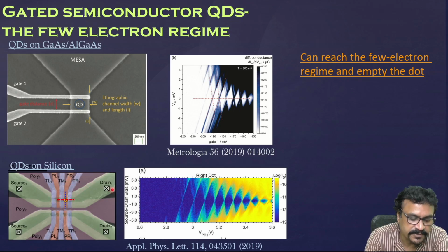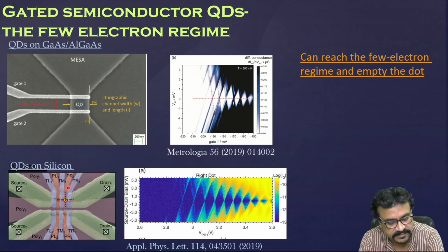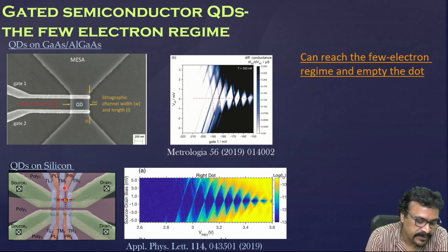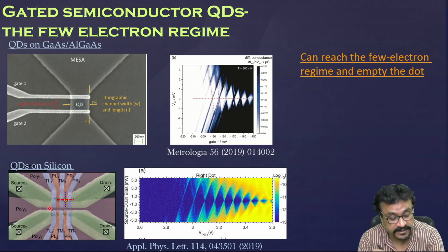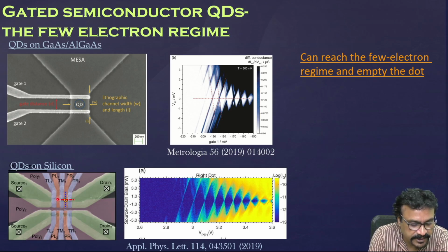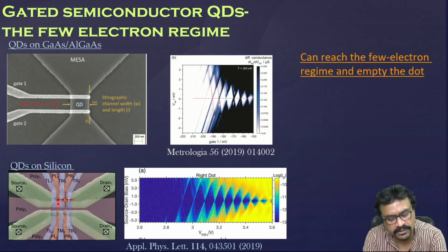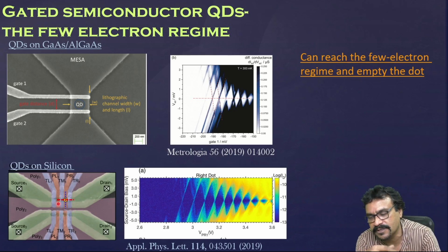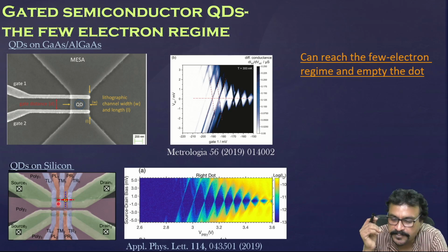This is an undoped system where you get electrons by applying positive voltages and you get barriers by applying negative voltages. Okay. So, this is a silicon dioxide system. You can get one quantum dot here, another one here, another one here. It's basically you have 4 dots in this one if you want, depending upon how you configure the voltages.